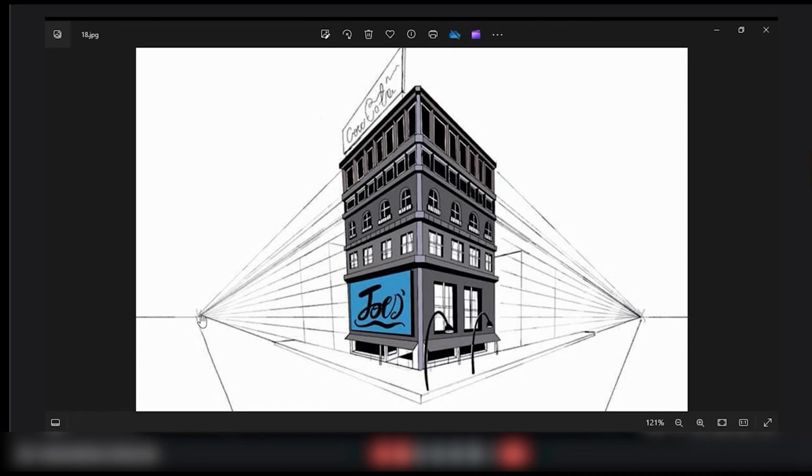A few angles you may call 10 degree, some angles are of 25 degree, 30, 60. Every kind of angle has been generated through these two focal points. Am I right? So that is why these kinds of 2-point perspectives are really suitable for portraying objects or the interior or exterior spaces from an angled perspective.